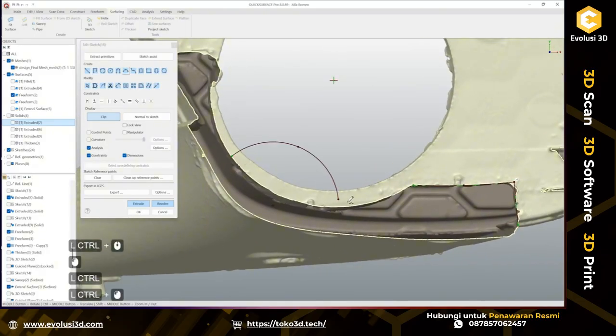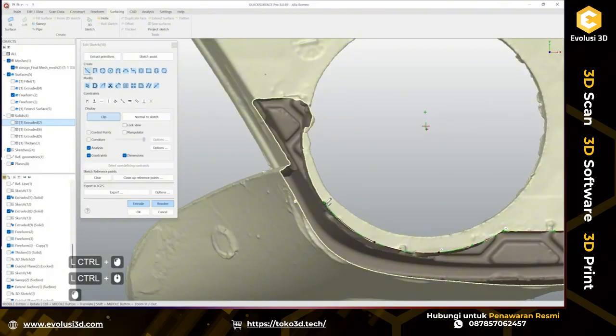This looks slightly more complicated because we don't have really nice scan data here, so it's a little bit junky. So we can go slightly freeform. Okay, so this one doesn't fit also, so I'm just going to create another tangent arc that could bend over close enough to my cross-section sketch. So slice point.